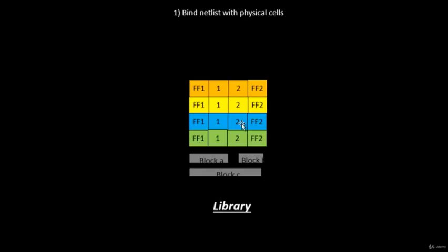The library can be classified into two sub-libraries. One library might consist only of the shapes and sizes, and one library might consist only of the delay information, but let's call it a library for now. So the library will have the following information. It will have the width and height of each and every cell. It will have the delay information of each and every cell, and it will have the required conditions of the cell. For example, at what condition does the flip-flop send the input to the output. There is something called a when condition. All this information is present in the library.